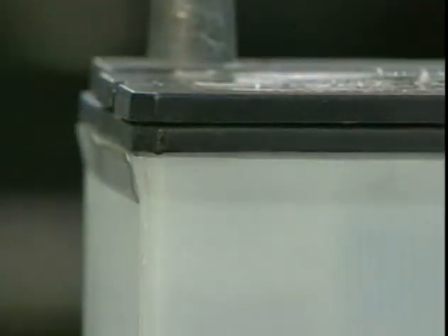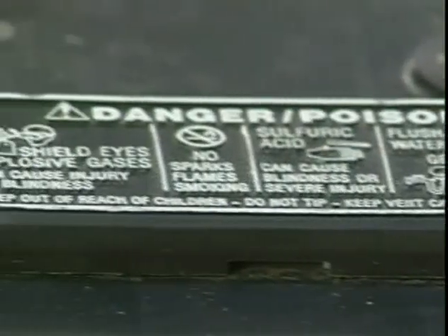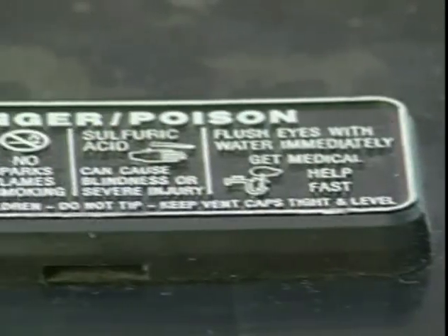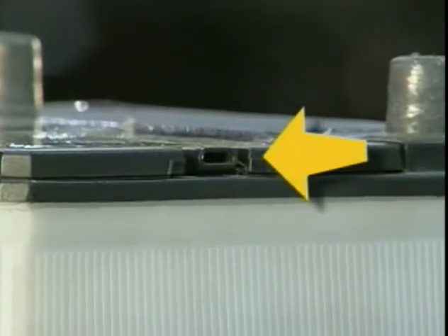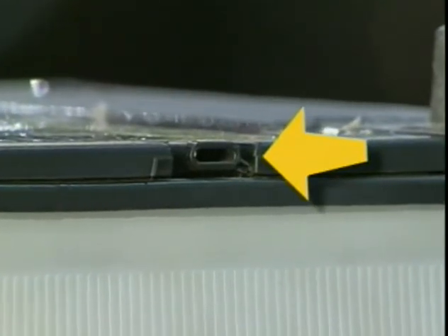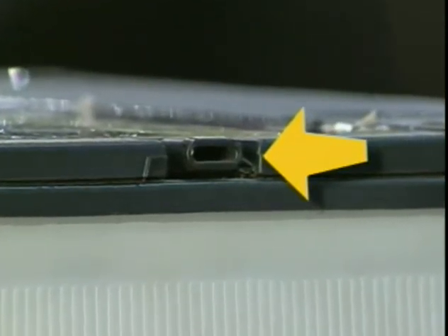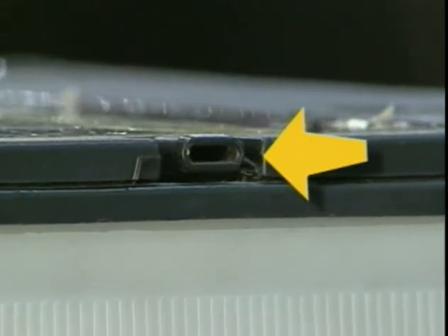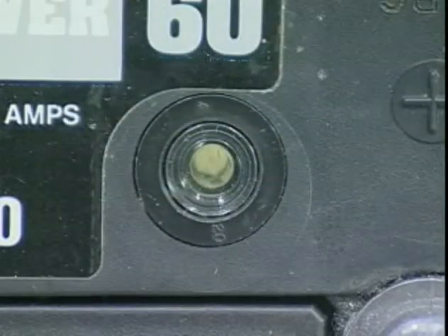The cover is heat-sealed to the top of the battery. If the battery is of a conventional or low-maintenance design, the cover contains cell caps that also serve as vents. On a no-maintenance battery, the cover contains gas vents, generally one on each side. A battery must be vented because of the expansion and contraction of its materials during temperature changes. It's also necessary to vent the gases that result from charging. A built-in testing device called a hydrometer is also included in the construction of the cover.